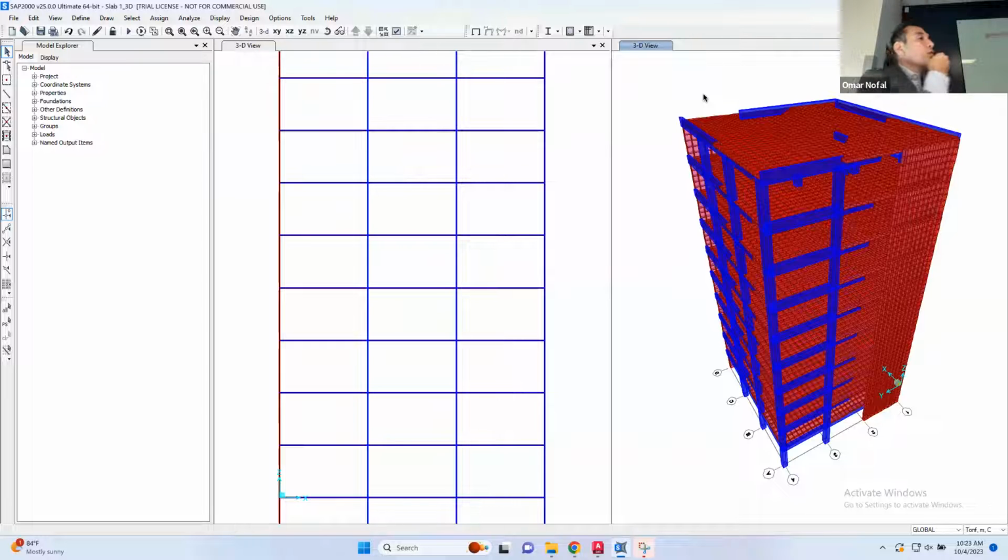Exactly. Usually when we design tall structures, everything is contributing and resisting lateral load. However, we neglect many things as a factor of safety, even the stairs. Do you know the stair system? The stair system is a very stiff system in your structure. Can you imagine you have a core and an element that goes this way and this way? It holds the structure. So the stair system contributes to the stiffness of the structure, but we neglect it in resisting lateral loads.